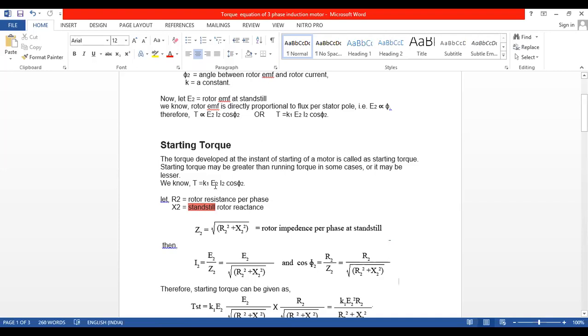Now you see here, all of you, the current we already know. Now I am bringing the definition of the current. Current I is equal to V by R. Everybody knows I is equal to V by R, but that is only if I have only resistors. In a room, if I have a fridge and a fan, I cannot write the current flowing through the room as I is equal to V by R. We must write I is equal to V by Z. Z is the impedance. I think in the first unit we have done the definitions of reactance and impedance; you must study that. Impedance is the total opposition to the AC current. So I is equal to V by Z.